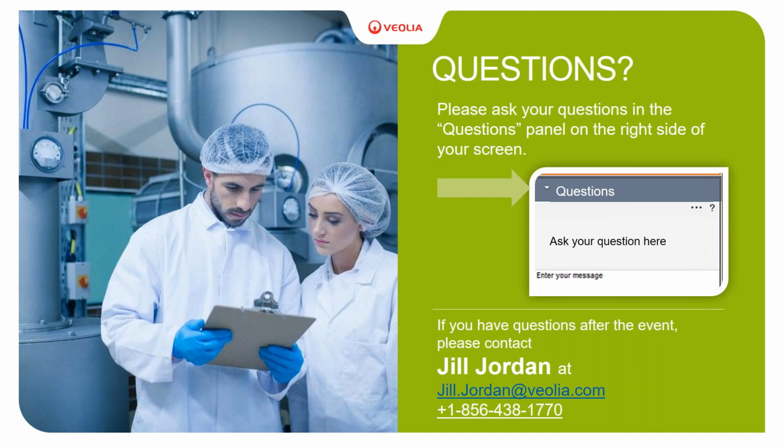Good question. There is a lot of municipal anaerobic sludge, but it's sludge that's generated from the solids digestion of primary solids and aerobic sludge generated at municipal plants, and therefore it has been exposed to sanitary sludge, which sometimes is not a good thing. In the food and bev industry you don't want that exposure in your reactor, because you want to be able to dispose of your sludge without having been exposed to sanitary sewage.